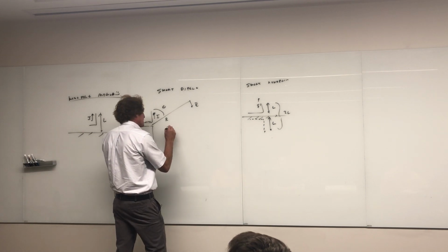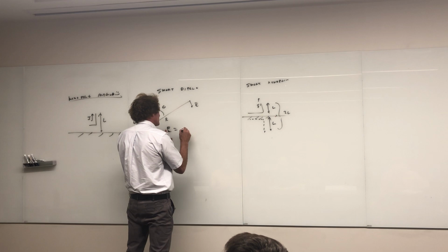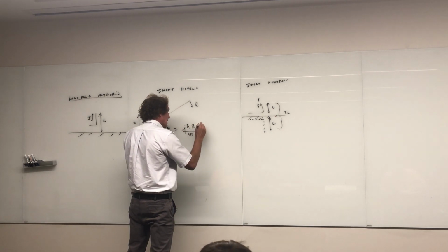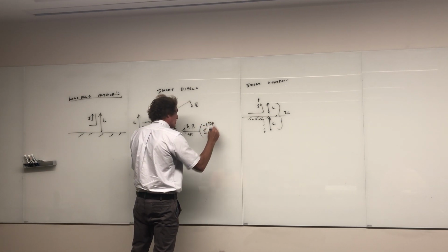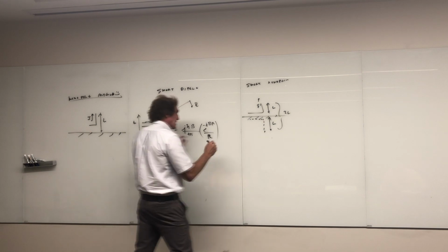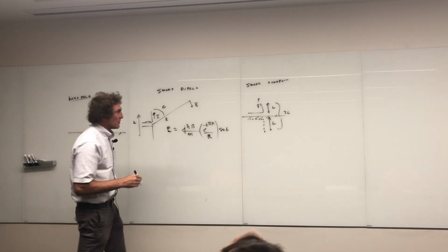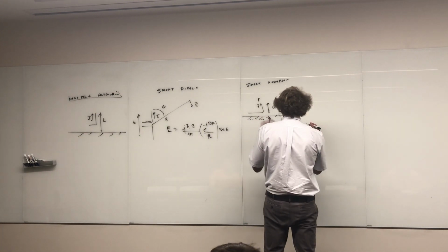All right, now the E field from this, and this is stuff you have to know, is going to be j eta beta over 4 pi, then the quantity e to the minus j beta r over r. R is just the radial distance in meters, but the angular variation is the sine of theta. That's the same for both. For a short dipole, the E field is going to be the same.